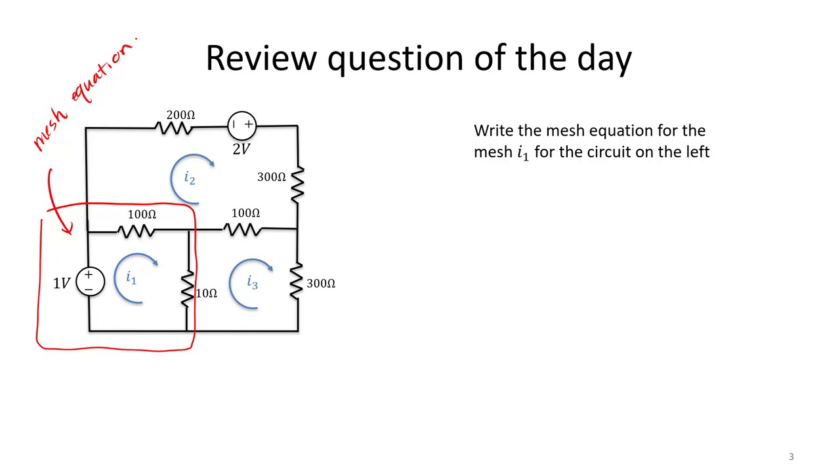Remember, when writing a mesh equation, you want to apply Kirchhoff's voltage law. And then you want to rewrite each voltage in terms of the mesh currents and resistances.